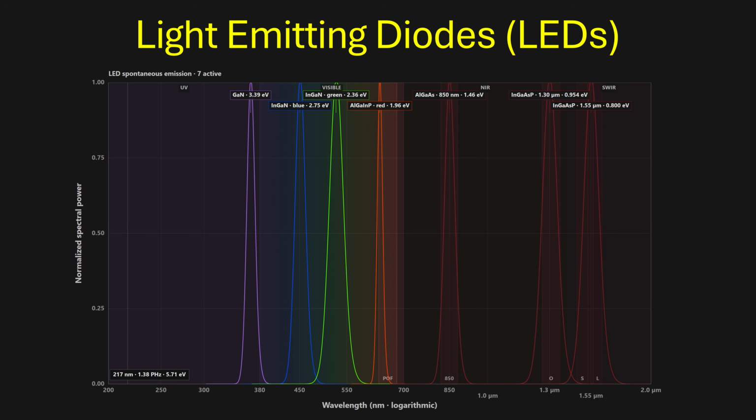So to produce specific wavelengths of light, the semiconductors can be mixed into alloys to create a specific bandgap, and these will have more than 2 elements listed in their name. You can see on this chart that the blue and green LEDs use the same type of alloy, and in that case, they just use different ratios of indium to gallium to change the bandgap.